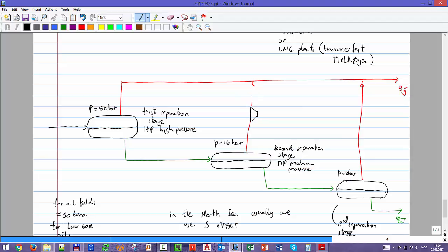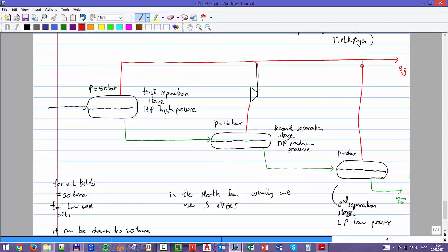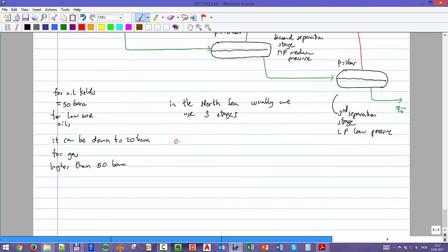Compressor, remember I enter into the big side, the wide side, and then I go out on the smaller side, indicating that initially I have a very high volume, and when I compress it, it occupies less volume. But I cannot do that exactly, because these machines, compressors, are very delicate and very expensive. Compressor can only work with gas, with very dry gas.